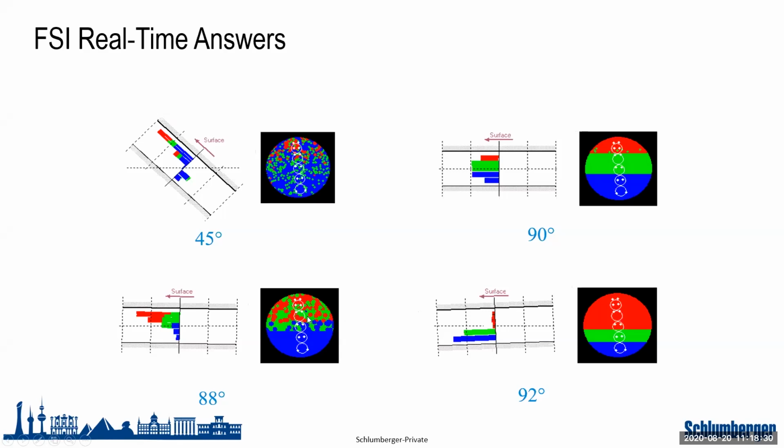Now, the same examples as the flow loop that we just saw in the previous slide. Let's say the 92 degrees. At 92 degrees downhill, we see that the water, the heavy phase, is moving faster, and the light phase, in this case gas, is moving slower and is occupying most of the area of the pipe. So gas holdup is bigger than oil holdup and water holdup, and this is a real measurement, real time by our tool.